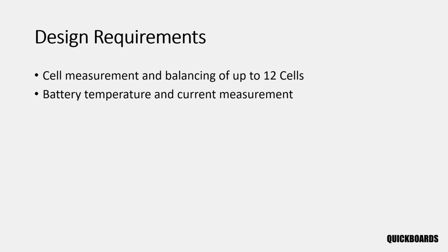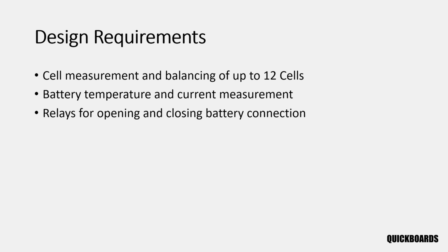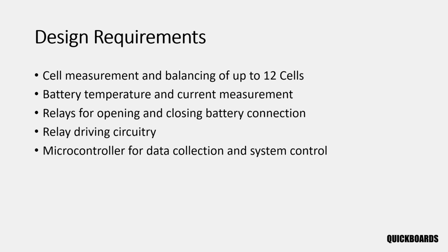To safely connect or disconnect the battery from the load, the BMS must control a relay driven by a dedicated relay driver circuit. For data acquisition, diagnostics, and system control, a microcontroller serves as the core of the design. And finally, to power all of these circuits, a stable power management stage is required.